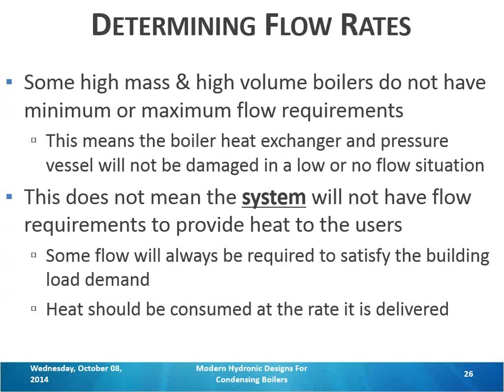What it is: our heat load Q in BTU an hour, our mass flow rate in pounds per hour, which we're going to convert to GPM, a volume flow rate, our c_p, which is the specific heat of the fluid. We're going to use water in this example, no glycol, so we're going to assume it's 1. It drops out of the equation. And then our delta T in degrees Fahrenheit. And we can simplify this through the conversion to GPM: flow in GPM is equal to our load over 500 times our delta T. Kind of the shortcut method to determining our flow rate.